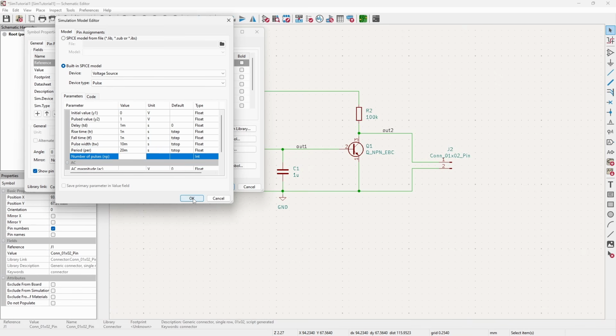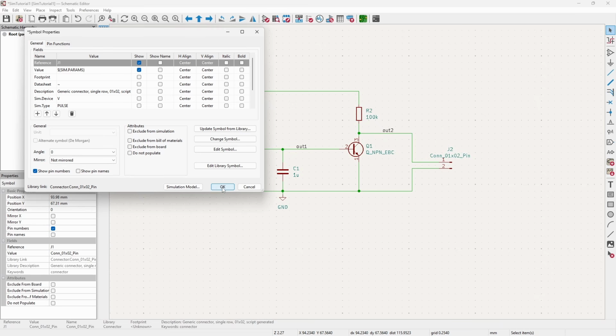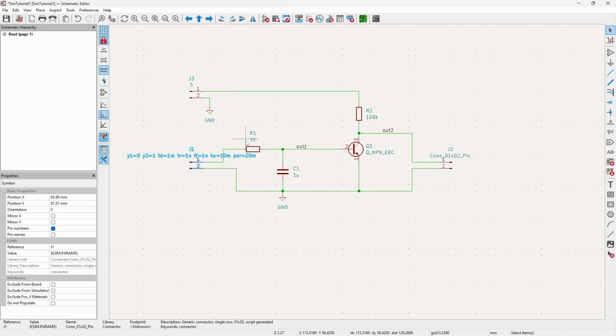And if you wonder how I picked those numbers out of the air, I have a 1K resistor, a 1 microfarad capacitor, so multiply those two together. It gives me my time constant of 1 millisecond. And I know that the rise time of a square wave onto this node is going to be about 5 times that, 5 milliseconds. So that gives me an idea of what time scale I should be operating at for this circuit.